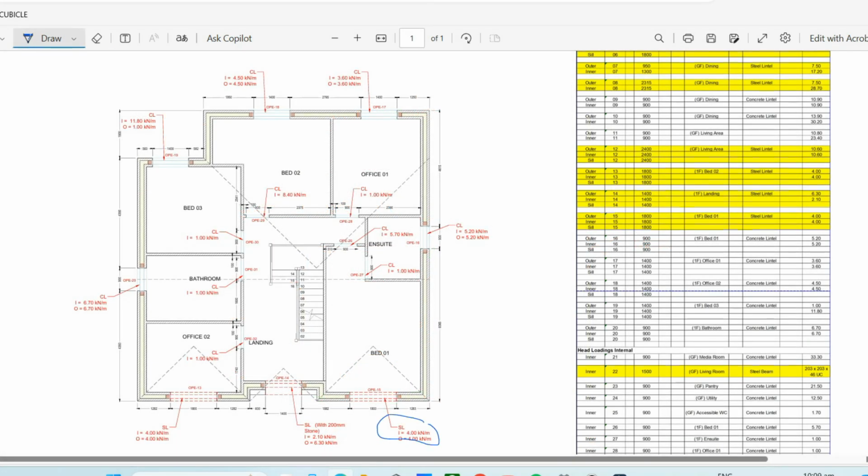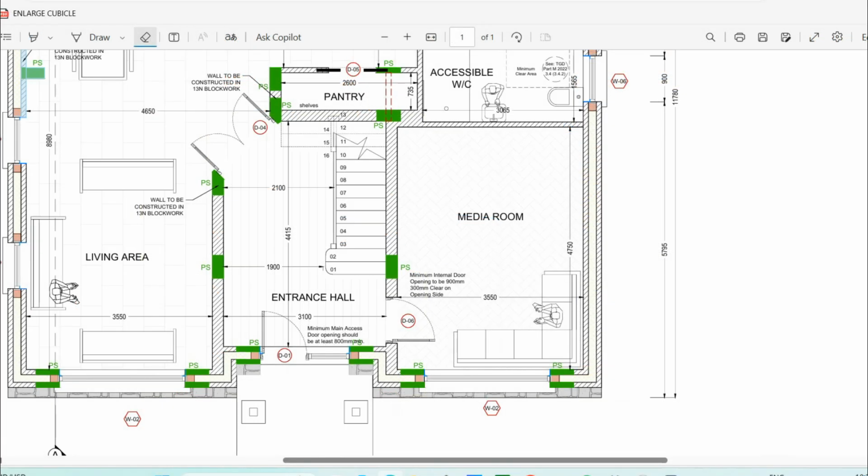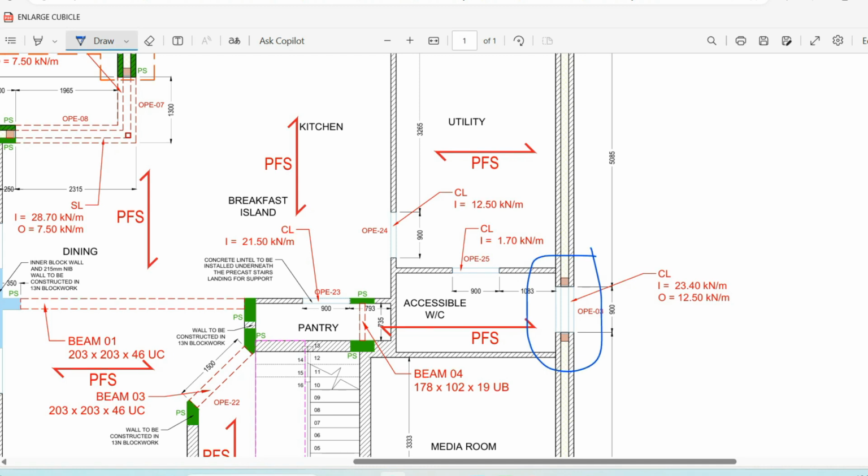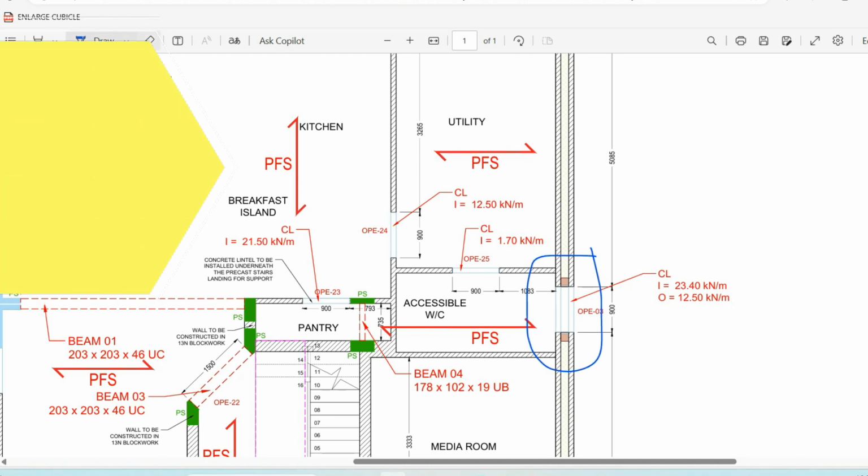And we will work this out so that we can recommend and put in a table showing the required loadings for a steel lintel or concrete lintel. If we take, for instance, the window here, because of the Irish regulations, this will either require a steel lintel, or a concrete head like the one shown, which will be above the 4 or 6 inch heads that are normally used, or maybe a 9-inch head.